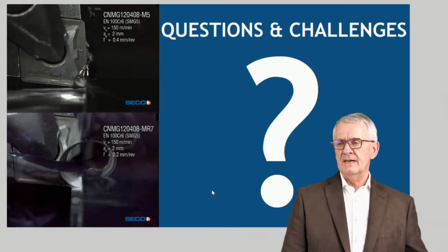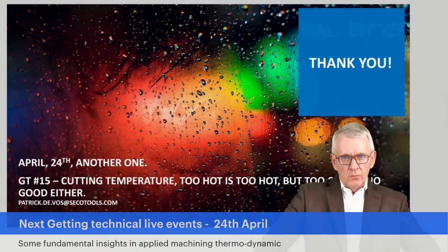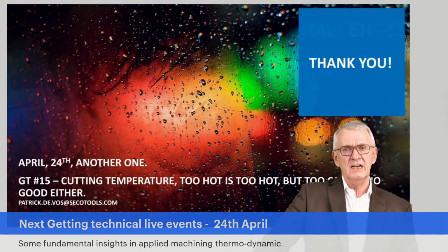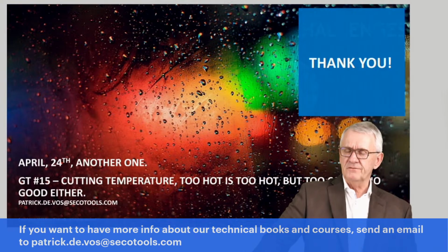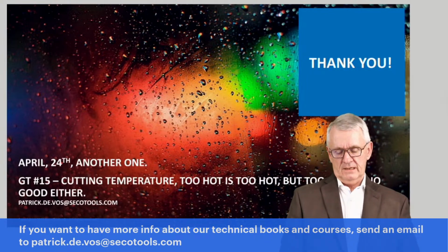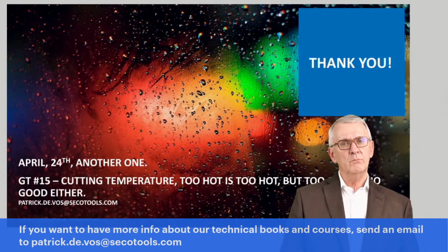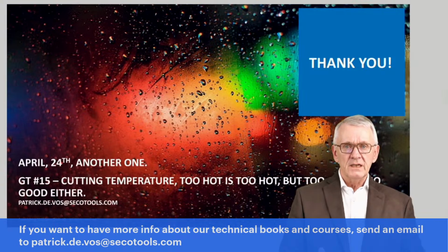My time is up. I hope it was an interesting hour. I hope I made you think a little bit about the importance of geometries. Perhaps next time when you have to select a tool for a certain application, you don't only spend time on cutting materials and the selection of cutting materials, but also think a little bit about the geometrical side of your selection. How does the tool look? What are the dimensions? Because the process itself is very strongly influenced by the geometry. And I can only repeat the statement made by Sam. If your geometry is wrong, no matter how hard you try, you can't make it a good machining process. It's as simple as that.